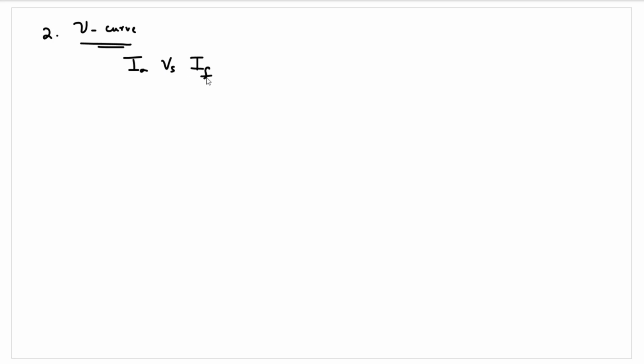These are the variation of IA versus IF in the case of the short circuit characteristics for a synchronous generator. Now IA versus IF is plotted for a synchronous motor, and that also for different power factor loads.